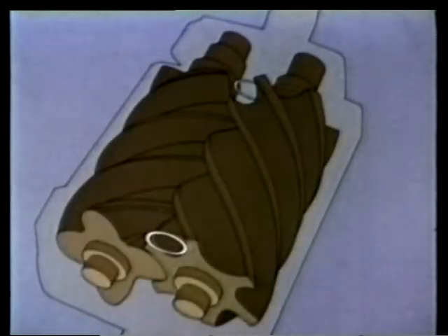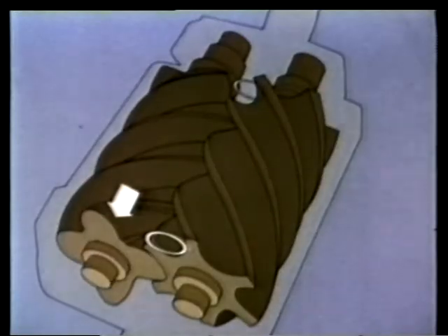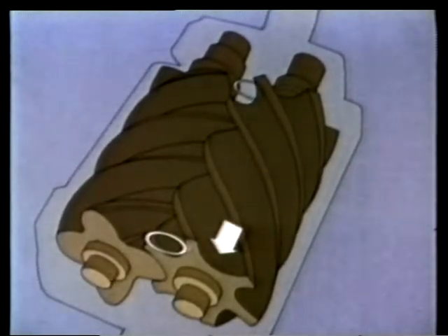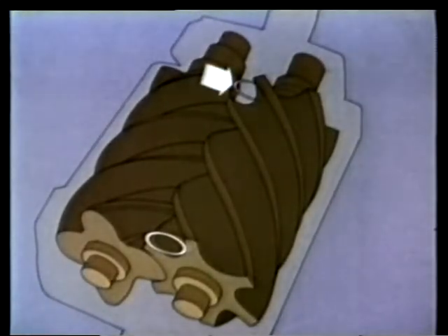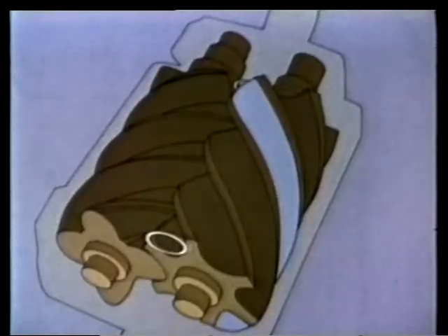Inside the casing of a typical rotary screw compressor are two rotors. A main rotor with 4 lobes and a secondary rotor with 6 grooves. Air enters the casing when a groove passes the inlet port. The air fills up the entire groove.